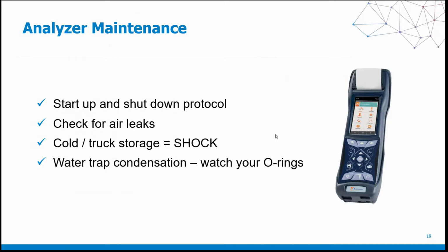Cold truck storage. Make sure that we are bringing our analyzers in at night during the winter months. I don't care where you are, as long as it gets below freezing, you want to try to bring that analyzer in at night, because it's like your cell phone. You're not going to leave your cell phone in a freezing cold truck and then stick it into a 300-degree oven the next morning and expect it to function properly. It's the same thing with an analyzer. An analyzer is a handheld computer. It's an electronic piece of equipment. It doesn't like heavy temperature fluctuations. It can shorten sensor life and shorten the life of the analyzer.